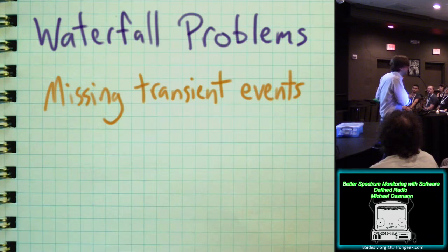Okay, you're getting 100 rows in 1 second, but each row was probably computed over a few hundred, or maybe, let's say, 1,000 samples. So 100,000 measurements are getting displayed on the screen in 1 second, at best. But there were 20 million measurements made in that second. You're only seeing 100,000 out of 20 million. And in most cases, that's probably the best case scenario. Roughly speaking, you're probably missing hundreds to maybe 1,000 times the information compared to what you're actually seeing on screen.